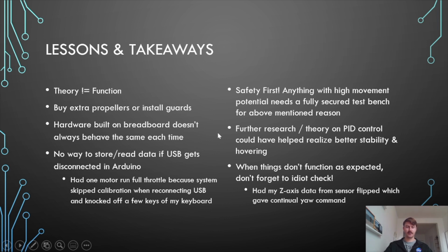One thing with building on a breadboard is that although it's nice and modular and you can rebuild something afterwards, the signal connection quality is a little less. I found sometimes I would be developing something, put it away for the night, and I literally wouldn't touch it, but I would bring it back to the test bench and it would have changed by the next time I tried to work on it. So although it has the benefit of being modular, the decrease in predictability of its signals was not as ideal.